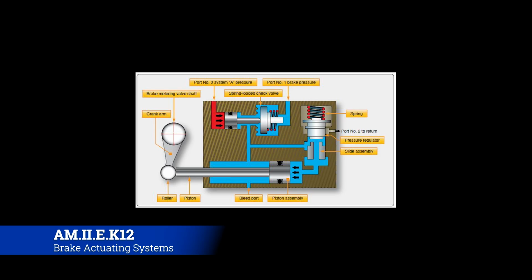You also have an auto brake pressure control system right there. It's simply monitoring the amount of pressure that's applied from the cockpit. It generally tries to apply the same brake pressure that the pilot wants to input, but makes sure that it's evenly distributed, with no spikes or anything wonky. Keep in mind that you can steer the plane with differential braking, so you want to make sure that the brakes are applied uniformly to both sides unless otherwise commanded.